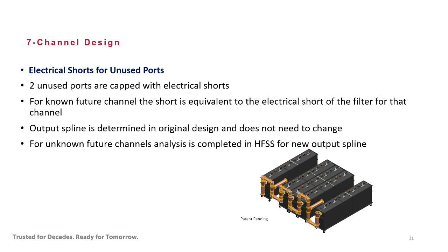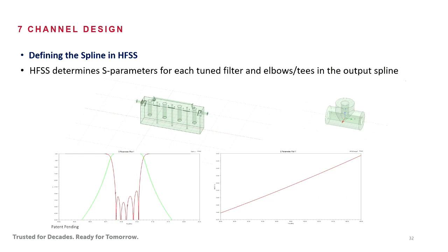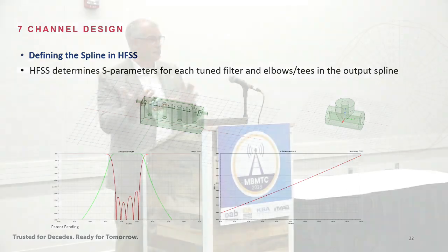So you think, well, how does HFSS help you? I mean, there could be thousands of different combinations and permutations here, right? Well, first, the data that goes into HFSS basically is the S parameters of the filter. So we characterize those filters in HFSS, and then, based on how many you want to put in this arrangement, HFSS and AIO determine, okay, what's the most efficient way to arrange those that uses the smallest number of different U-links to achieve that performance.